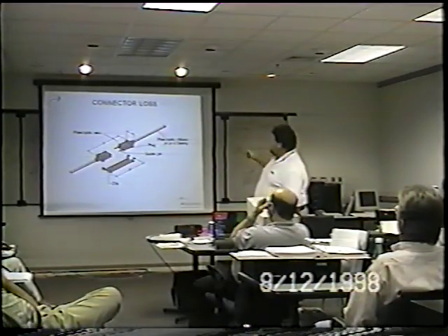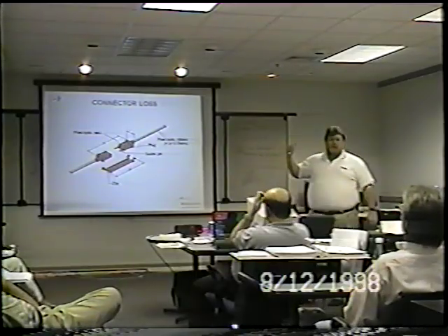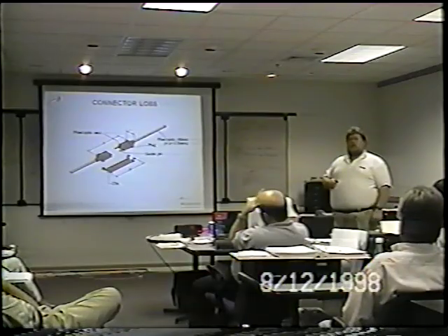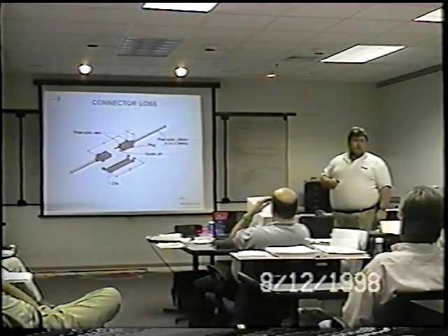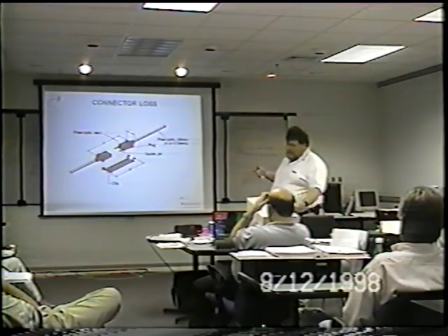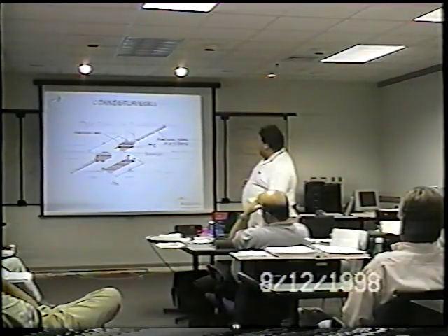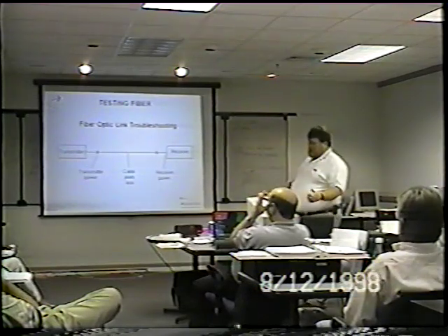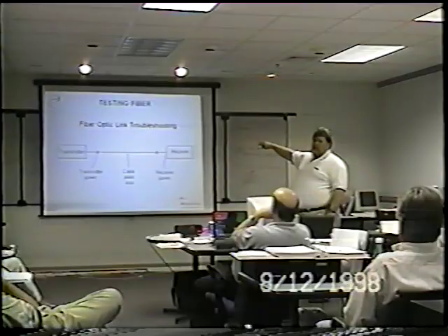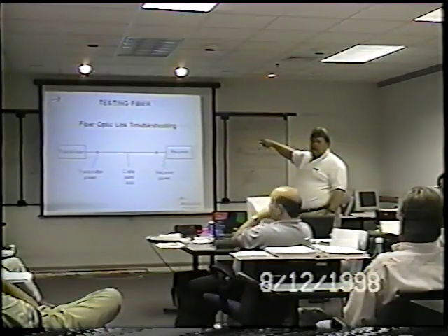Connector losses. Another big contributor too is in the office complex: under-carpet cabling, modular fiber components, stuff that gets dropped down the wall and stuff like that. Those are incredible sources of losses there. Okay for multimode and short haul stuff, but when we get into other things, it's a big issue. This is probably some of the stuff we're going to talk a little bit about tomorrow while some of the breaks are going on in the lab.